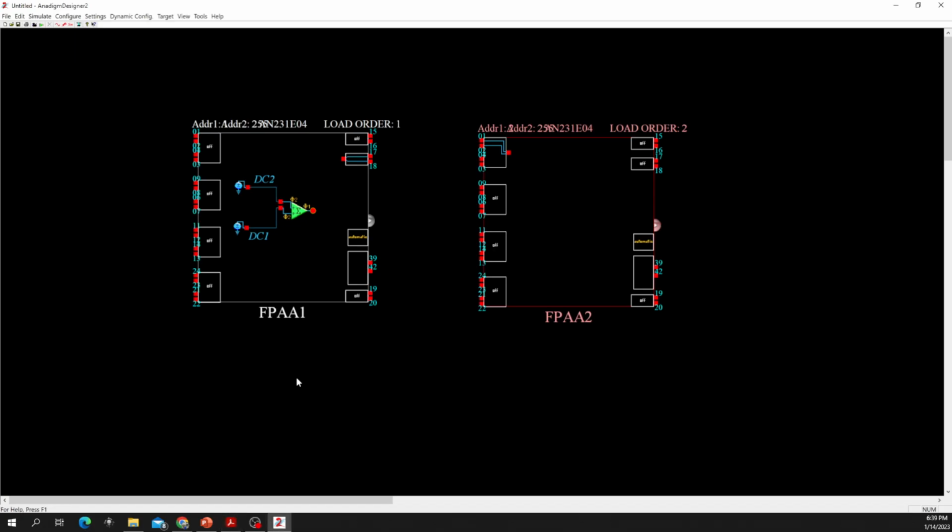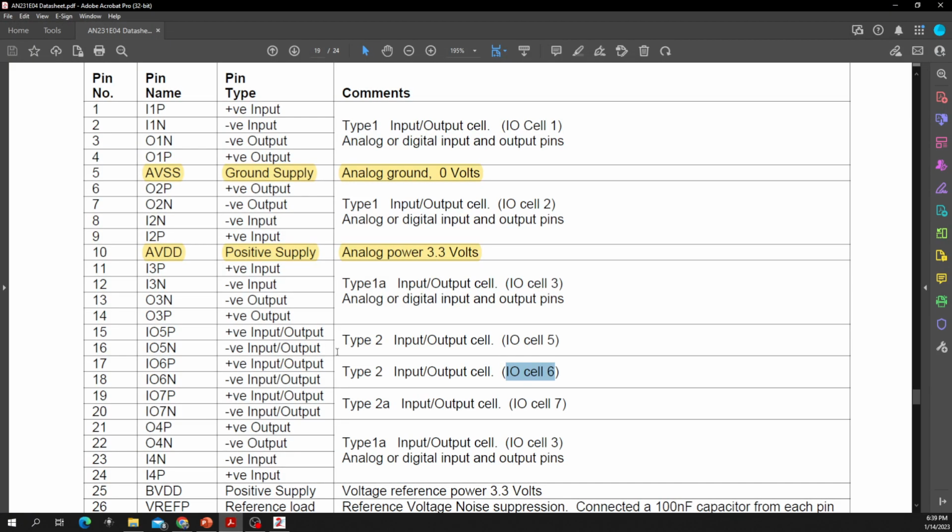And then, okay, you were wondering, 17, 18, 17 go to 1 or 2. Let's make sure they match. So 17 means plus, right? IO6P. P means positive or plus. And 1 also means P, right? That means plus goes to plus. You shouldn't have any sign mismatch.